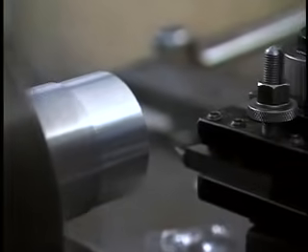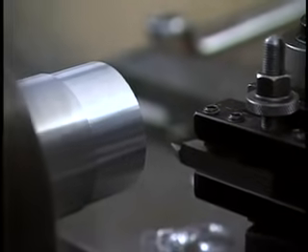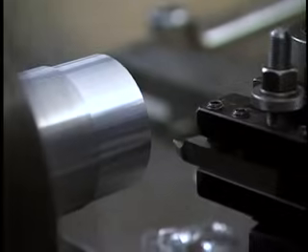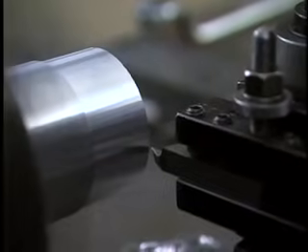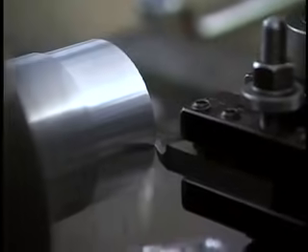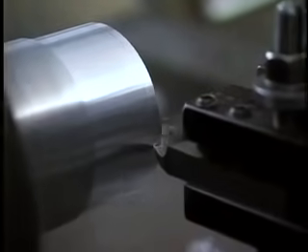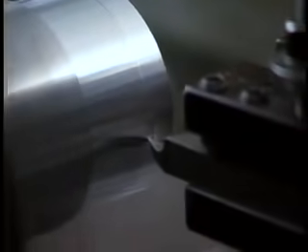I bring the tool away from the part, engage the power feed, again to make sure nothing very exciting happens. Make sure that the feed is going in the right direction and the speed that I thought it was going to be moving at. Now, having assured myself that the machine is set right, I can bring the tool up close to the part and engage the feed. You can see by the difference in surface finish, and also even here, that the cut is proceeding much more smoothly using the power feed than it was when I was feeding by hand.